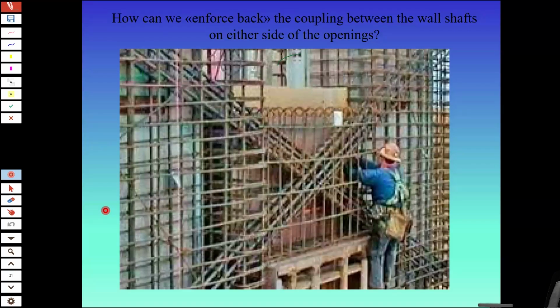The other main thing, you see the opening is here, and the other opening is here. So you can imagine this is the coupling beam, from the top of the door up to the floor of the upper floor. And they have to work at this edge cross section. But it means that from that edge cross section onward, they must be bonded into concrete. So from that point onward, you need to calculate the development length.